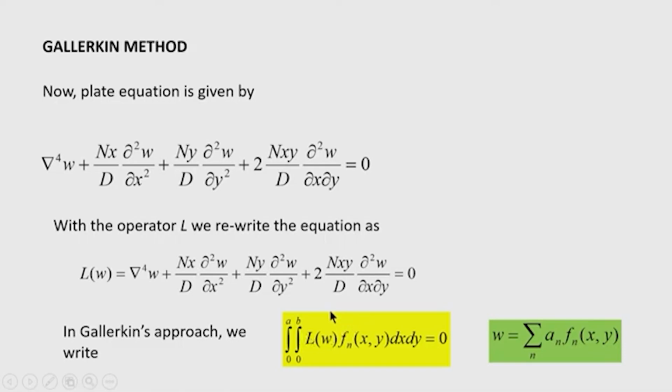Now, here you can see the shape function is approximate; sometimes we can choose the exact function. Say for example, in a simply supported plate along all edges we take the Navier's series, then it represents the exact deflected shape. So, therefore, the function is exact.